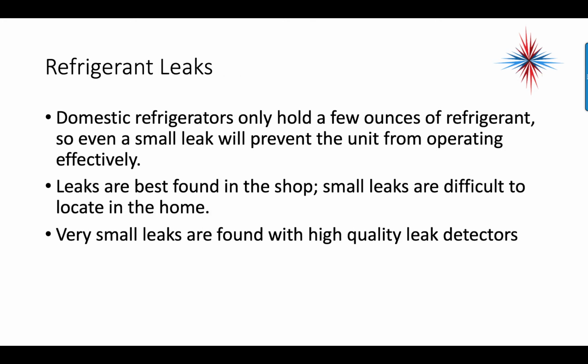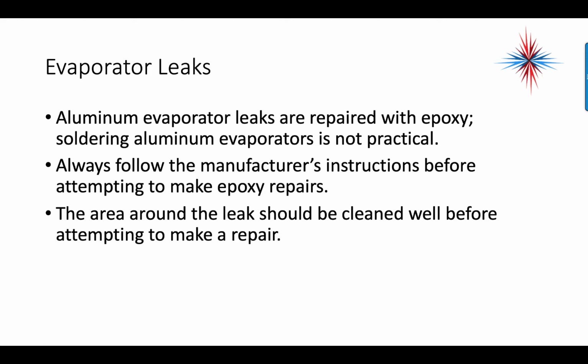domestic refrigerators. Domestic refrigerators only hold a few ounces of refrigerant, so even a small leak will prevent the unit from operating efficiently. Leaks are best found in the shops. Small leaks are difficult to locate in the home. Very small leaks can be found with high-quality leak detectors.